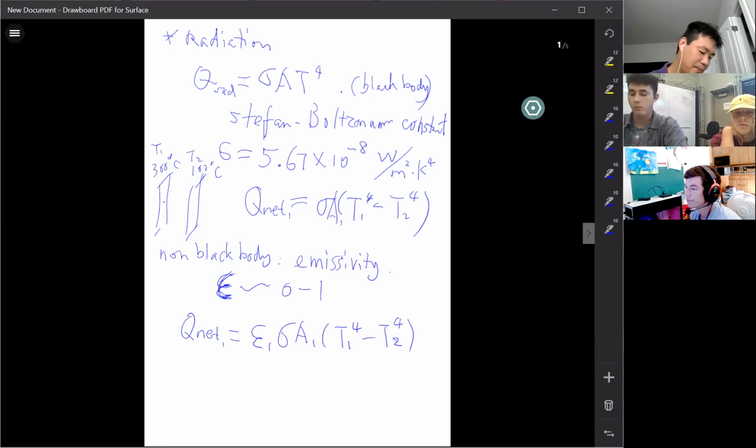Good. Barely has a black body, close to black body, I think. Most of them, the emissivity is less than 0.5. I have several of them. Nickel oxide surface is 0.59 to 0.86, one of the higher ones. And nickel alloys, nickel wire oxidized, is almost a black body, 0.95 to 0.98. So that's a table you can use for the actual calculation.